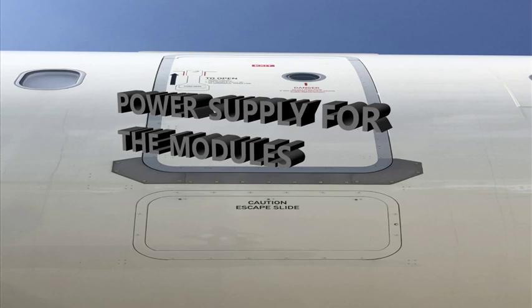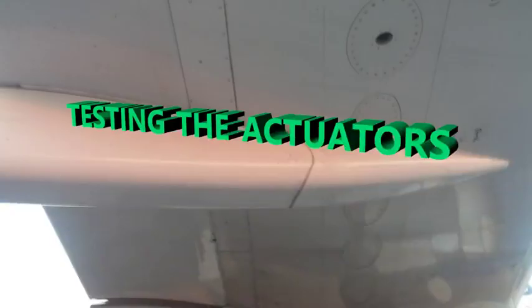Now remember I said about testing. You can test the actuators. When you're on the ground, you can test and actually operate the actuators. Of course, in order to do that, you need to pressurize something, otherwise you can't do the test. So you do need to have at least one hydraulic system pressurized and one engine running.